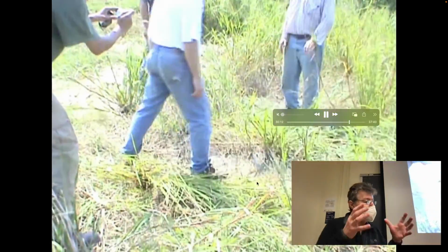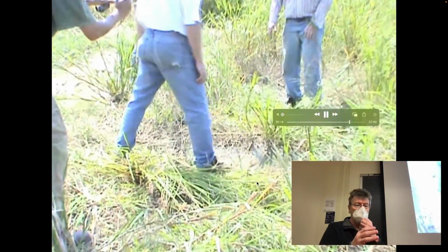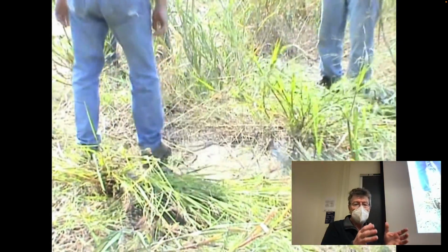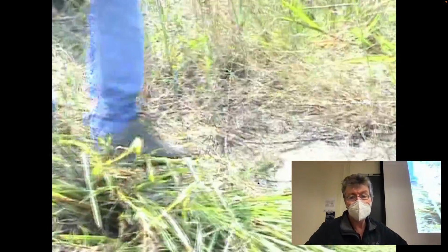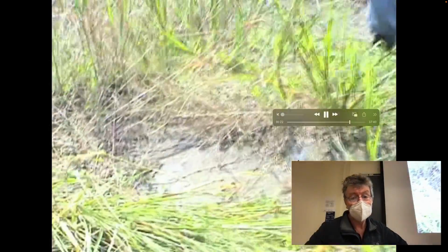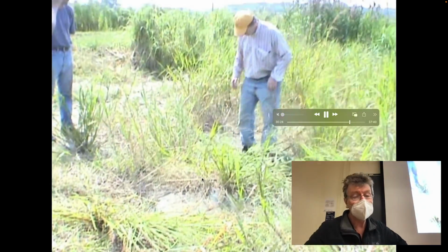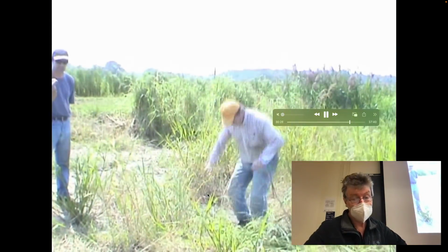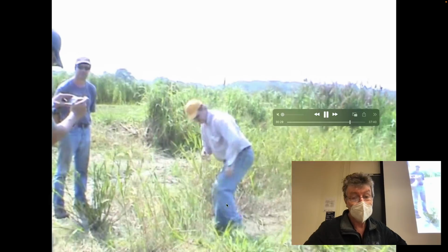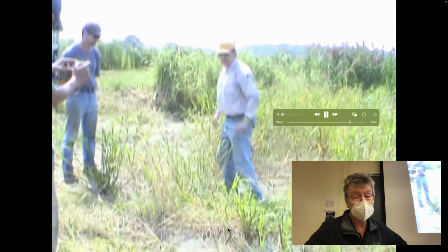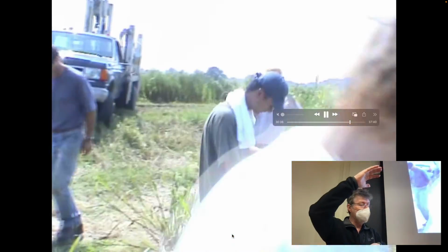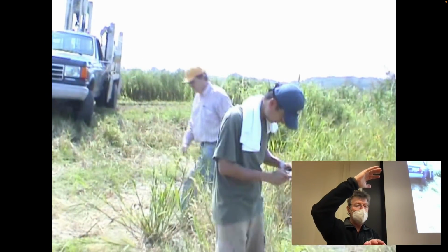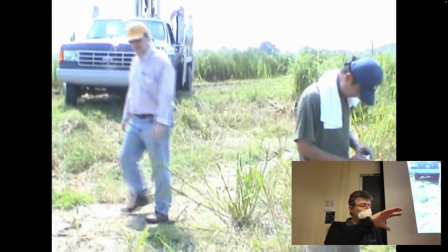But as soon as the big heavy cone truck came on with the bass low frequency vibration from the engine, it liquefied all the material. Fortunately, not all the way to the surface, because the truck was on there, and my truck was on there at one stage as well. But basically underneath here, it's just like a spring mattress. Probably there'd be a foot of solid crust, which is dried out here. Below it is water saturated